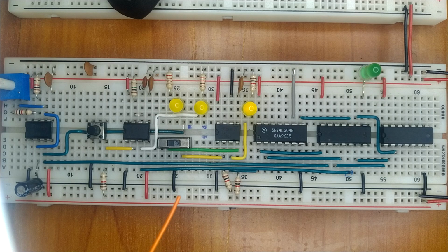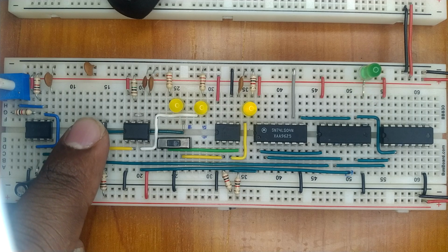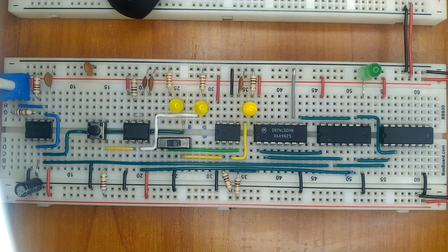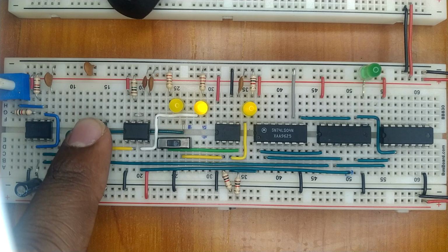Now the second state is the monostable. The monostable has only one state. It's only stable in one state. So this is the chip that controls the monostable state. If you look at this chip, pin number 3 is this white wire. It goes like this, and then it goes to this LED. For this 555 timer, I've connected this tag switch, whereby if I press this switch, the LED comes on. I release, the LED goes off, meaning that it is only stable in the off position, like that.